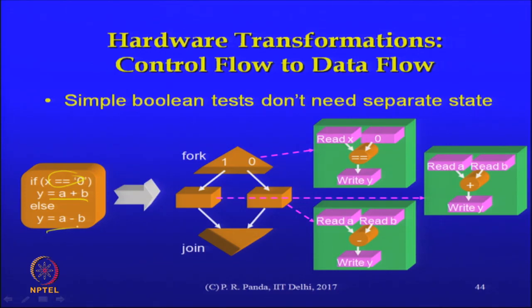This we had already seen, since there is an if statement that translates to that fork join structure in the IR. What is there in the fork join structure? Each of these nodes translate to a respective DFG of that basic block. So, y equals a plus b is this basic block, y equals a minus b is this basic block. Then I have that condition that also in the general case might have its own expression that may need ultimately to be merged with the prior basic block like we had seen earlier. But that is what the general CDFG structure looks like.